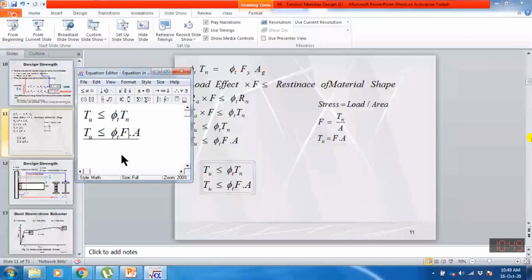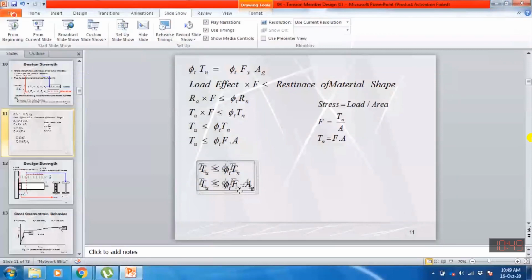So I have to use the strength of steel as Fy. Yielding failure means that which is occurring due to yielding. And yielding will always occur at gross area. Gross area means that which is available for most of the length. So this will be my first equation: yielding capacity at gross area should be more than or equal to applied load.